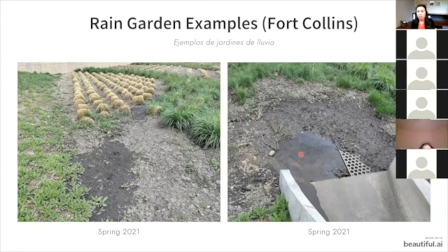What you're getting here is a mosquito breeding area. And so you don't want that to happen. There's not enough erosion control that was put here. And so that's why you're getting this undercutting of this cement right here and causing this pool of ponded water.